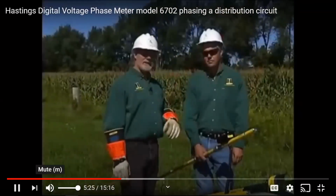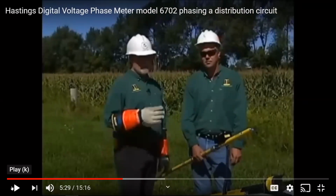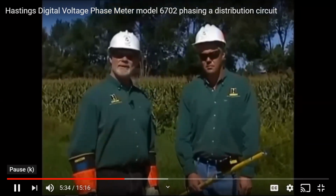Purpose of this segment of the video is to high pot underground cable. Okay, so what did he call it? High potting. All right, you need to write that down in your notes. High potting underground cable. High potting is short for putting something, whatever you're testing, to a high potential. High potting equals high potential. So we can determine the integrity of that cable and how the meter reacts to conditions of the cable.